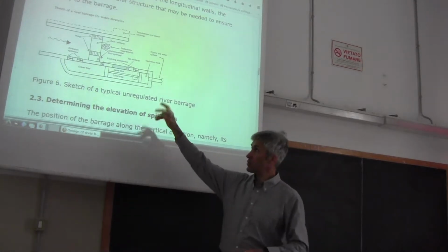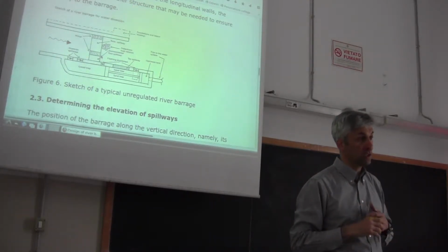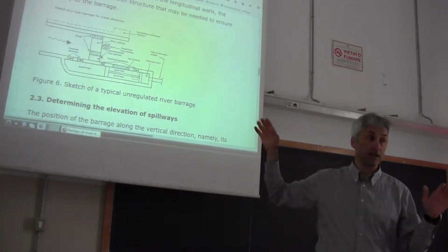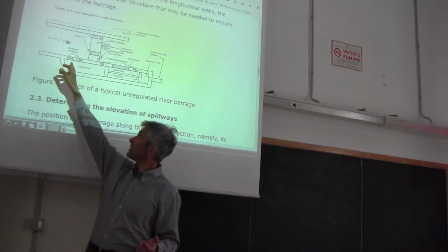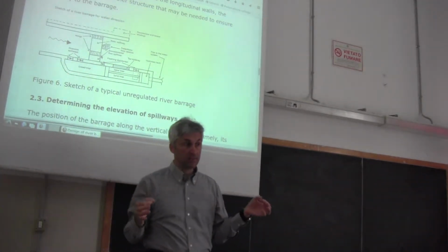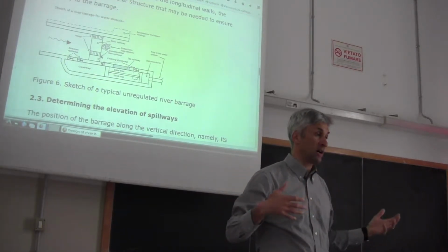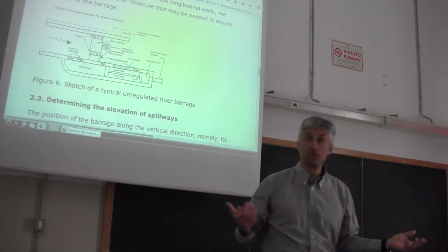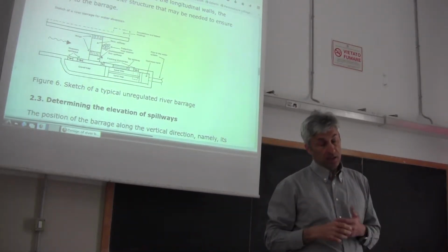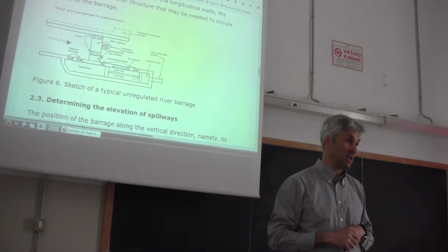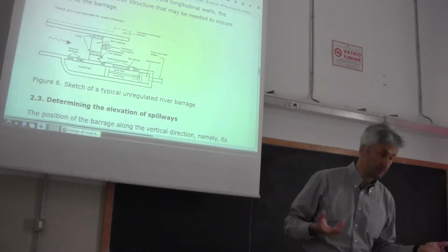And therefore we discussed the structure of a small barrage, which is not automated, meaning that there is no control of the flows. It's completely running alone, without need for control. Even if we said that when we look at the diversion spillways, we put gates there, which are useful in order to regulate the withdrawal and in order to allow cleaning or other maintenance operations. And we said that these gates can be remotely controlled. And nowadays the solution of making the gates remotely controlled is becoming more and more diffused, so we can manage the diversion without the need of sending people there. And this is, of course, useful.